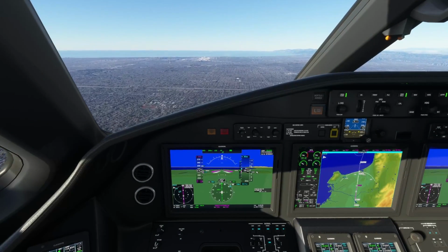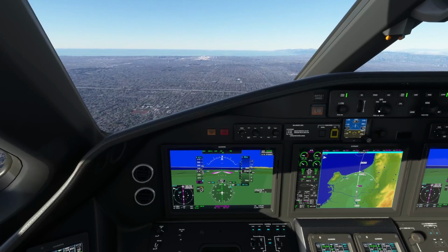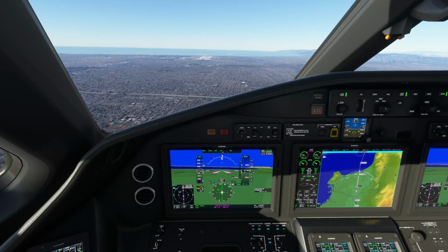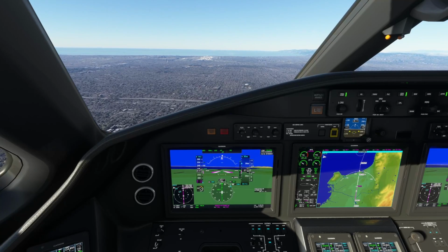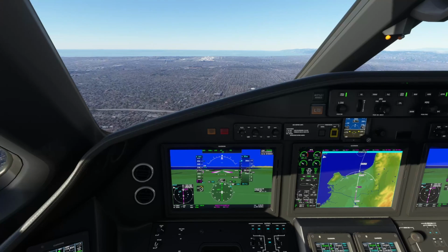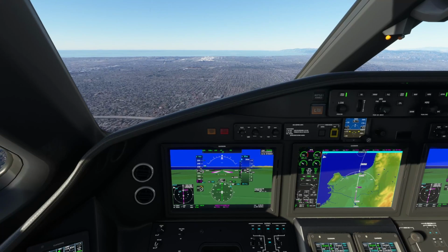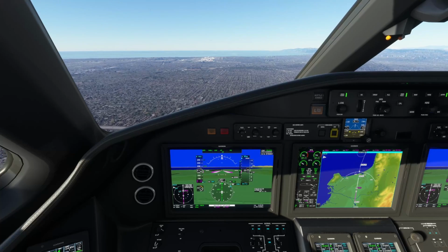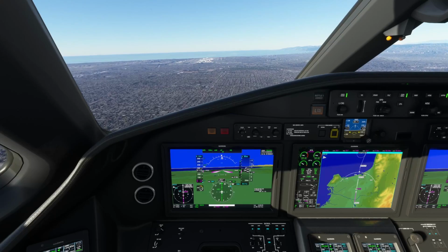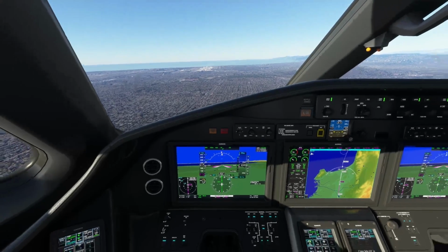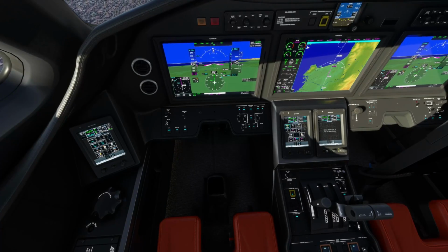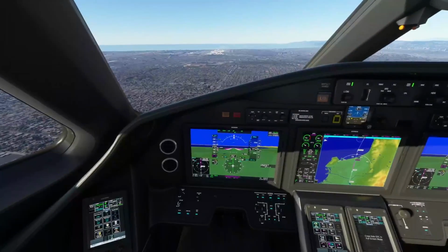So the first thing we're going to do is go flaps 1. I'm actually going to put the speed back over into manual mode now. We've seen it work. It's working beautiful. And I'm going to start slowing us down to about 150 knots. You got to be allowed to have some fun here. And we're not slowing down near as fast as I want, so we're pulling that speed brake out, because flaps 1 are already set.